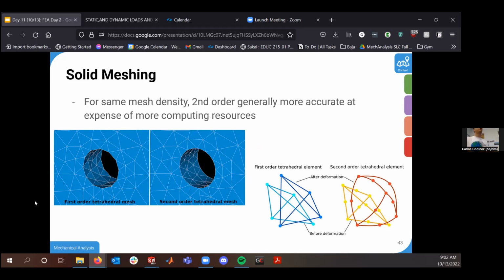So when you're doing quick and dirty, where I just want to run my study and see if it gives me something laughably unbelievable or within reality, I would do that, and then I would switch to a higher quality mesh element instead of draft, or increase my density, and then walk away and let it solve for like 6 hours or something.